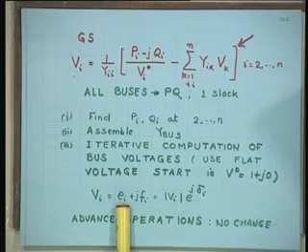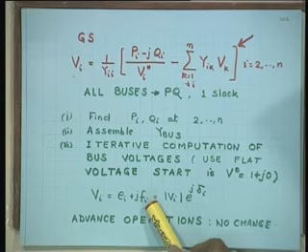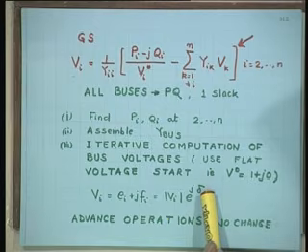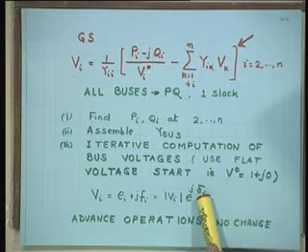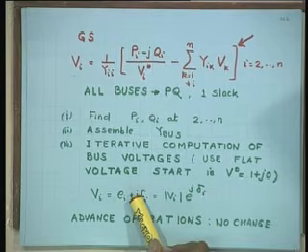What is the plus point here? The rectangular version, Ei plus jFi, at times gives better convergence, but this is more practical. What you can measure with a voltmeter is a magnitude, but what you actually get is an angle. So this is more practical, and convergence-wise, the other is slightly better.